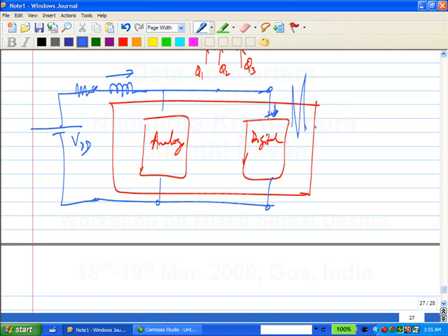So what do you think will happen to the voltage here? If there is no inductance, there is no problem. If there is inductance, what happens? Supply bounce or ground bounce. So why is that happening? That's happening because the inductance cannot tolerate a sudden change in current. So if the current here changes suddenly, what happens? The voltage across the inductor is L di by dt, correct? Di by dt is infinite or very high at any rate. So this voltage will attempt to fall down, right? Ideally it is VDD, but every time there is a clock transition it will attempt to fall.